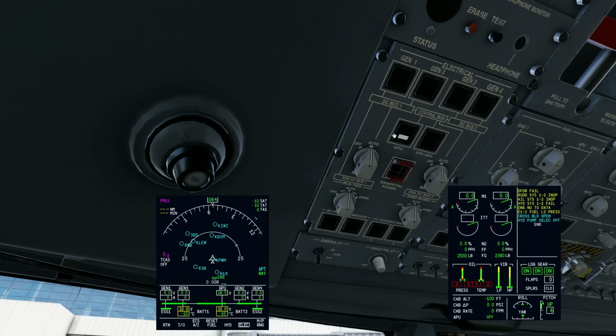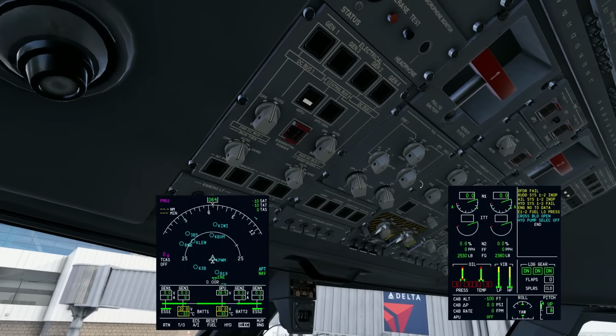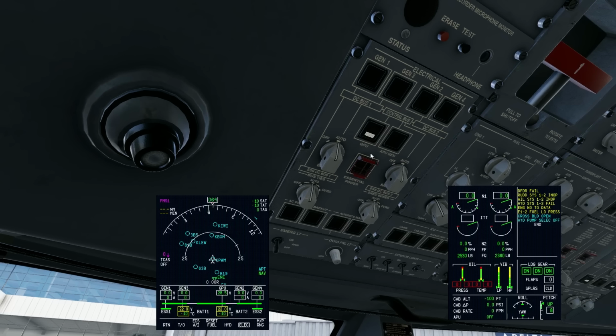Something important to know for people new to Embraer is that we have a dark cockpit philosophy. It's similar to an Airbus in the sense that when everything is normal for flight, so remember, normal for flight, if a panel is configured the way it should be according to the aircraft logic for flight operations, you will see no lights. No stripes is what we call them. So, makes sense, right? Unless you're towing the GPU, and I sure hope you're not, you would not see a GPU stripe while you're in flight. This is only a ground item, otherwise known as non-normal for flight.